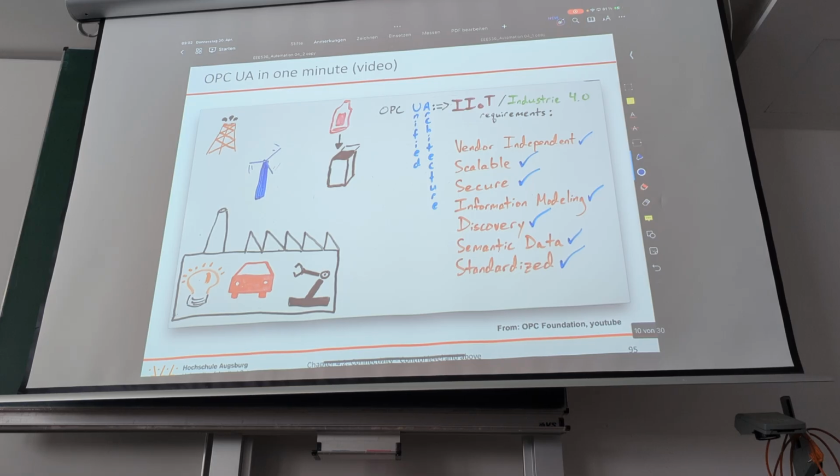So by now, yes, all these systems support OPC UA, but once you are in older machines, 10 years and older, most of the time you don't see modern OPC, but rather classic OPC, and that's why you still have these old Windows machines there and you can't update them. Yeah, that's how it works in the automation industry.